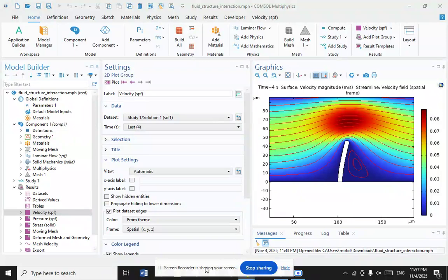And what about the numerical simulation? A Newton-Raphson method or a different fixed point iteration can be used to solve fluid structure interaction problems. Methods based on Newton-Raphson iteration are used in both the monolithic and the partitioned approach. These methods solve the nonlinear flow equations and the structural equations in the entire fluid and solid domain with a Newton-Raphson method.